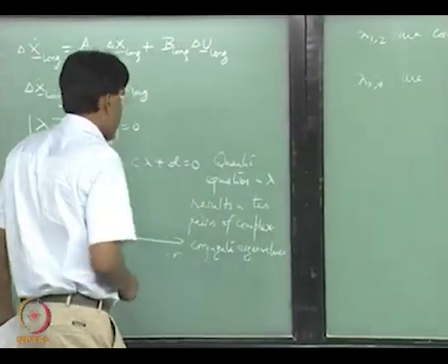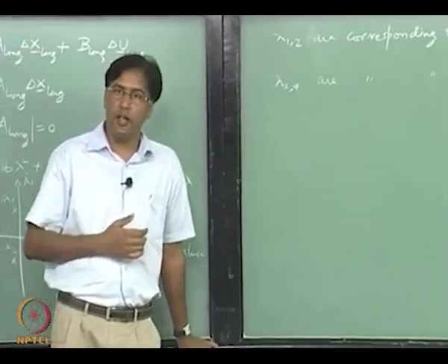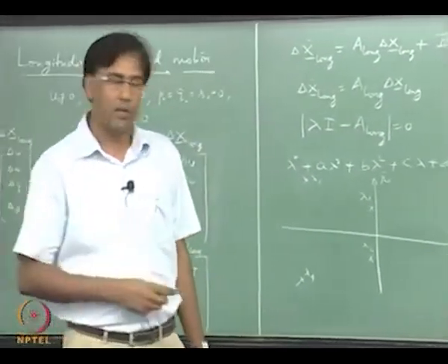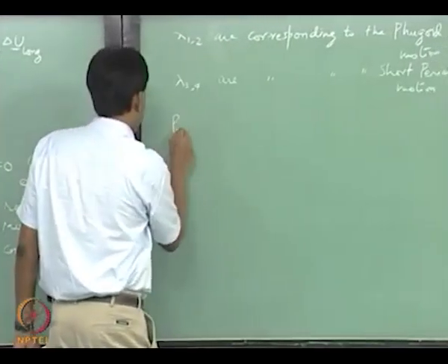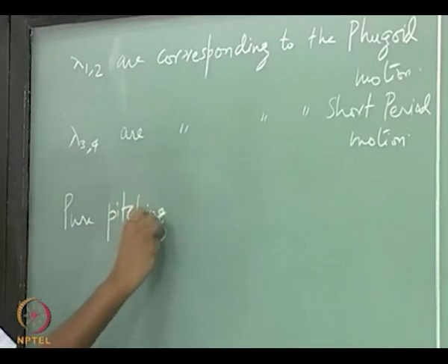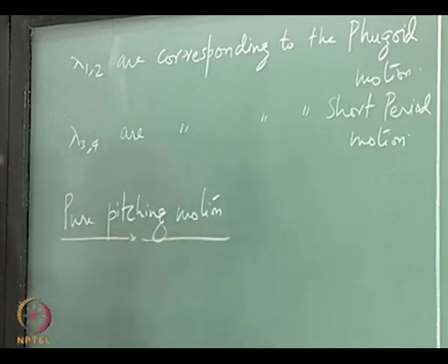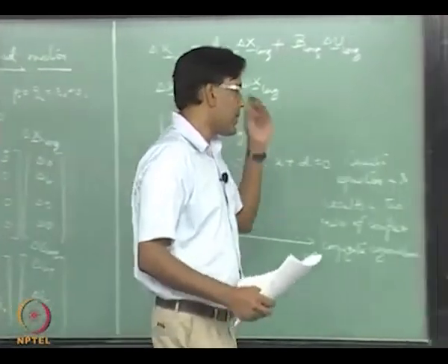So, what we did yesterday, we assumed the short period mode to be a pure pitching motion. So, we looked at pure pitching motion of aircraft about this flight condition, right.